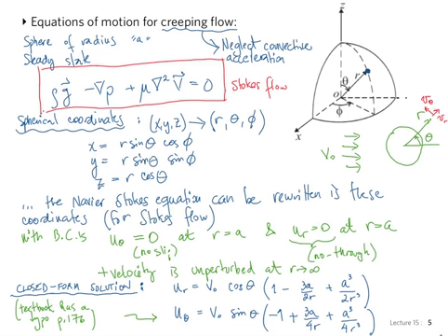It's a very famous result by Stokes, and there's some interesting things to say about it. Note that the velocities, which we find in closed form, are independent of the viscosity. For Stokes flow, things are moving so slowly that any viscosity is almost the same. It's independent of the viscosity, and this is pretty much true of creeping flow.